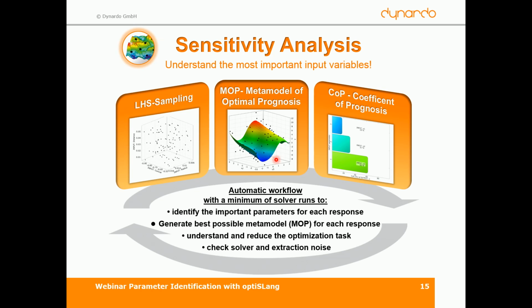The MOP does some other important step. It finds out which of the input parameters are very important for the model results and which are not. And you see here with the ranking which are mostly important and which are less important. And so we come out with a set of most important input parameters, the unimportant parameters filtered out automatically, and we get a ranking which shows the really most important and less important parameters.